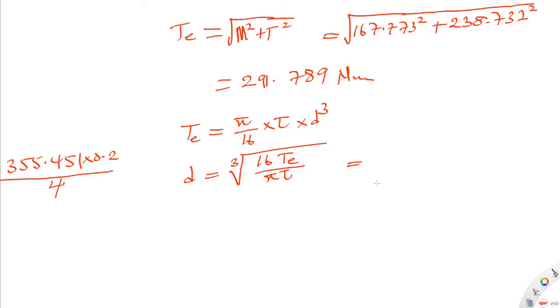That is the cubic root of 16 times 291.789, divided by the allowable shear stress, which is 45 times 10 exponent 6, times pi.